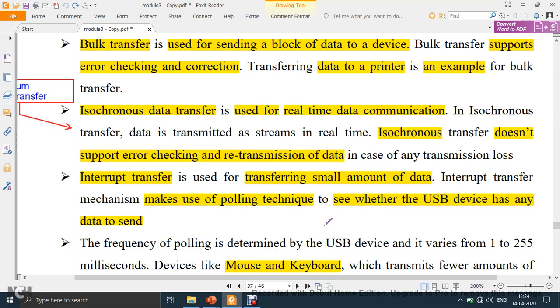First, let's say you check line number 1. If there is some data to transfer, you will transfer the data. Then you go to line 2. As soon as you go to line 2, line 1 and the other lines are not activated. Only line 2 is activated, and if there is some data to transfer, it will be transferred. Like that, all the lines will be checked serially, one after the other. The line being checked is the only one active, the others are inactive. That is polling.